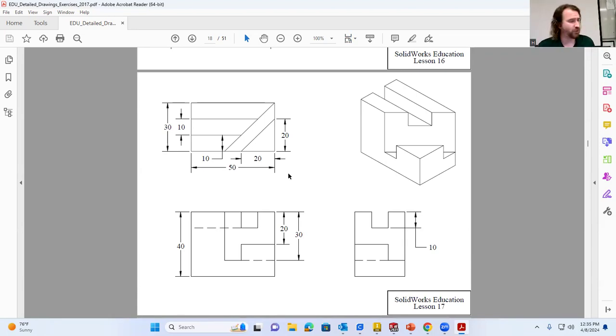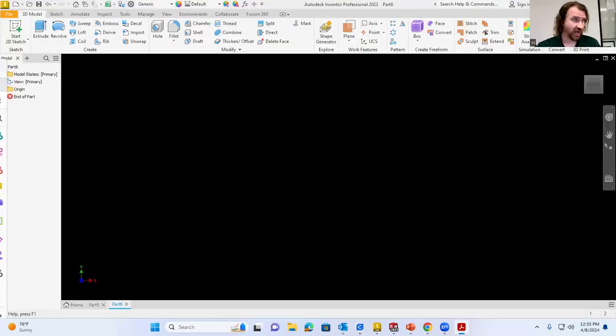So as we pause there for a quick beverage, we are going to look at this top view. We're going to draw the outer perimeter, which is just a simple rectangle, and then draw these lines in here to section everything off and make all these profiles. We have a triangle, this parallelogram, and these other ones kind of going down. Each one of these profiles is going to be extruded a certain height up. Let's move this off to the side so I can view that while sketching.